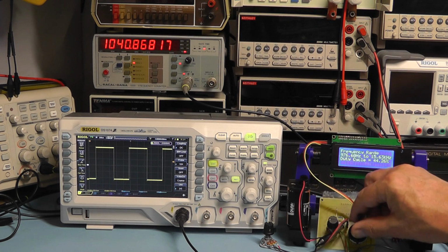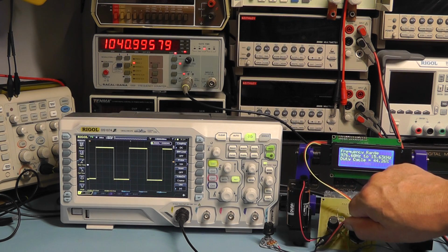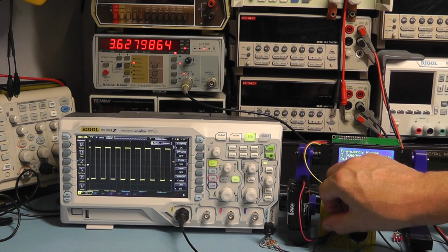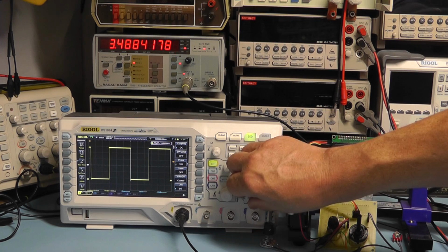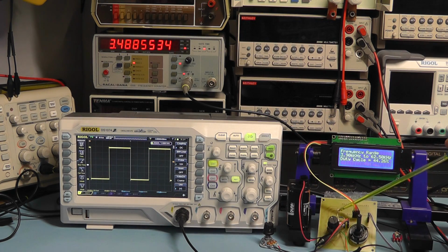To alter the frequency, I'll just step it up in frequency again, so it is much more stable if I earth the casing of the potentiometer, so it's obviously getting pickup if we don't earth that. But I may look at using a different type of potentiometer, but a quality one, as we finalise this little project. But for the moment I'm going to leave it there, and in part 2 we'll have a look at ways of trying to overcome some of that instability at the higher frequency end of this little pulse generator that we've built.